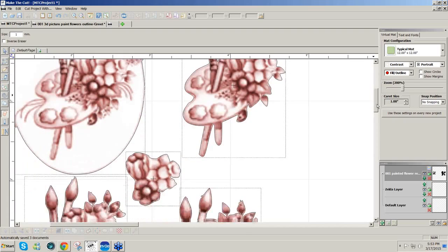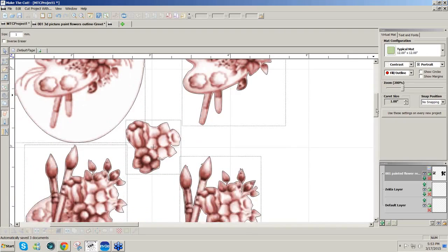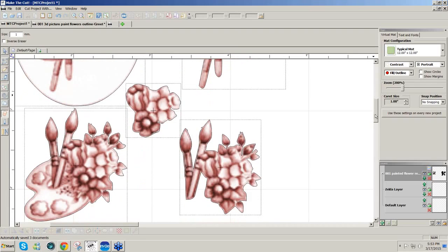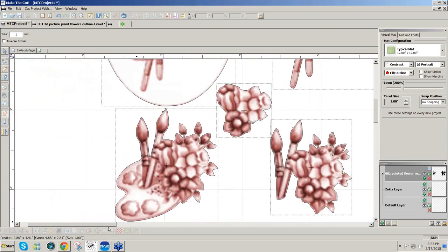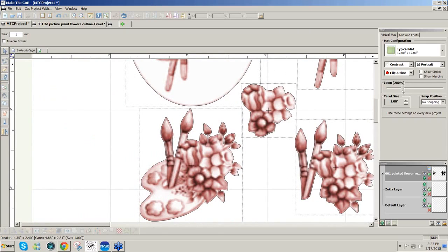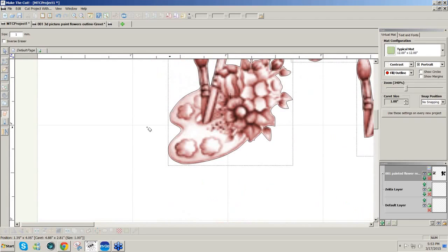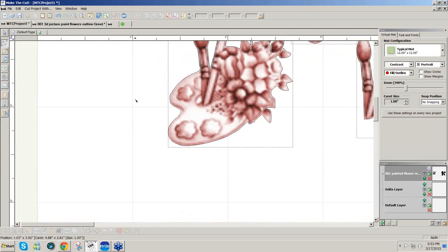And I'm looking at all these design lines to make sure that there's no little white pieces showing that I would rather not have showing. For example, over here, I could make that line hug the edge a little closer by clicking on this node editing tool, the second arrow.